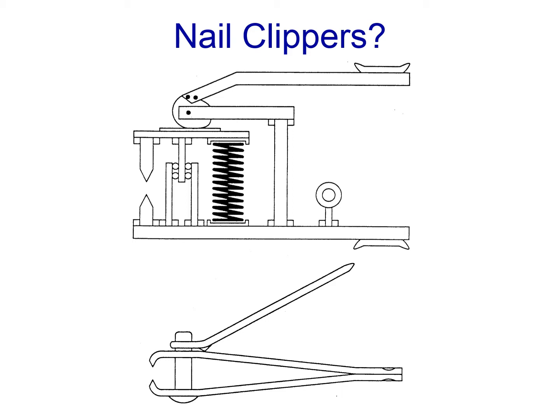The top one exhibits modularity, obviously. The bottom one is integral. In what ways does the upper clipper exhibit modularity as compared to the lower one? In the upper clipper, each physical element implements a function. The spring implements the pushback open function. This is where you push, right here. This is where you hold a keychain, for example. These are the blades. Maybe they are sharpable or replaceable.